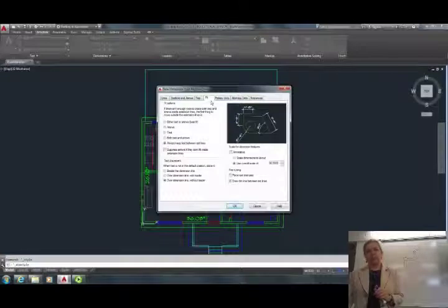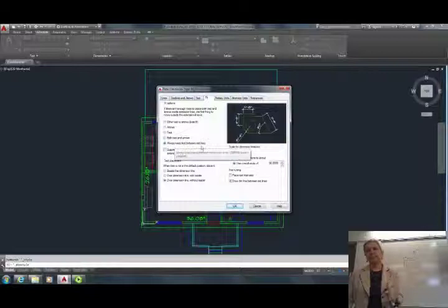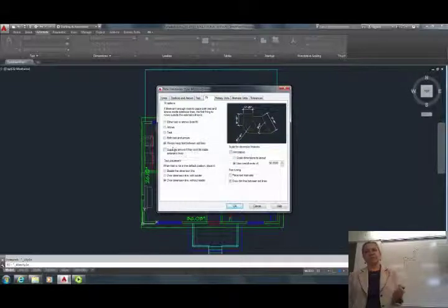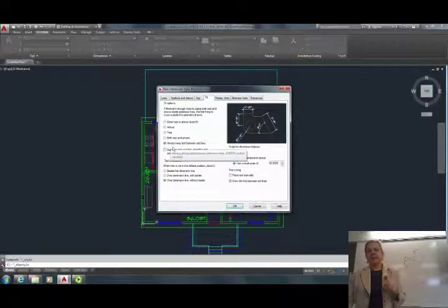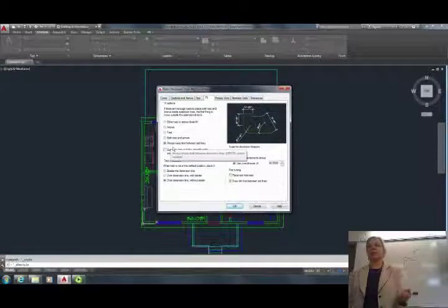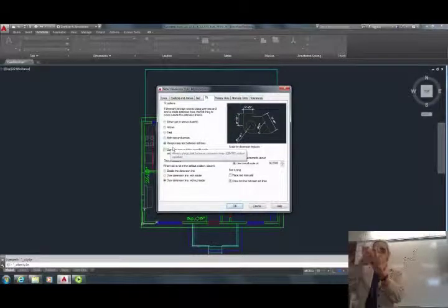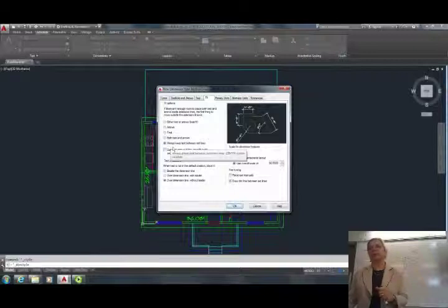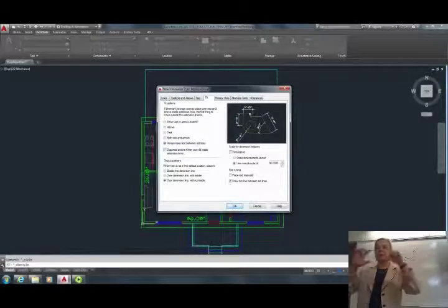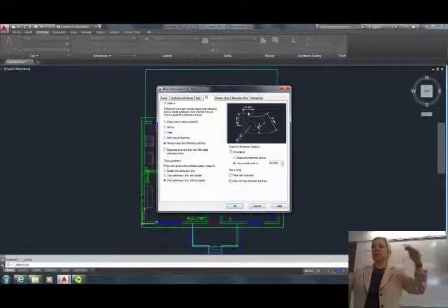You always want to keep text between extension lines. What does that mean? It means that if you start from the standard dimension settings, the standard default is designed, AutoCAD was designed for mechanical people working on one-to-one models of engineering parts. So mechanical drawings are done differently than construction drawings. Their dimensions sit between the line, like the line is broken and the dimension sits between dimension lines.